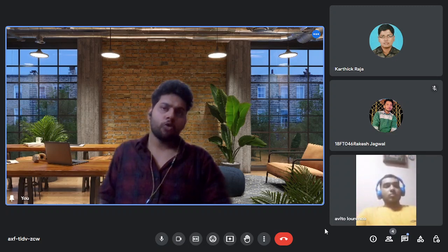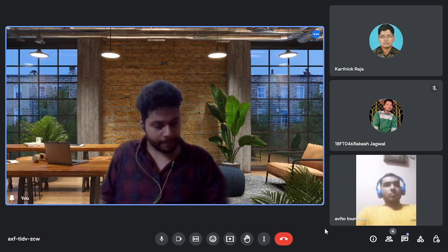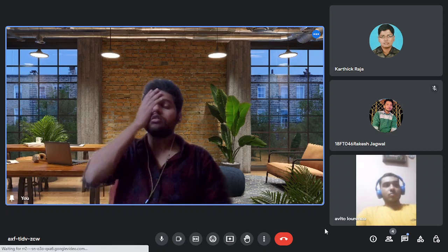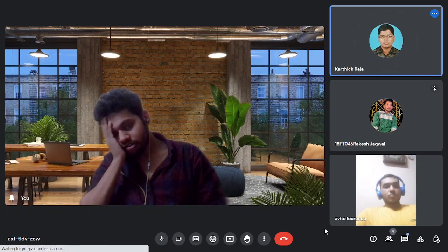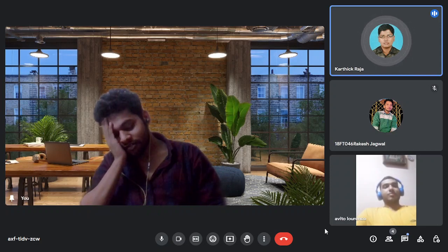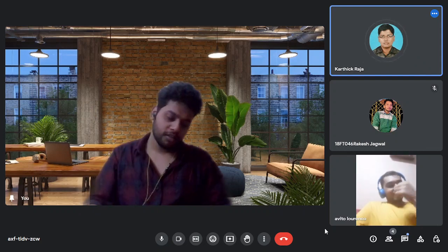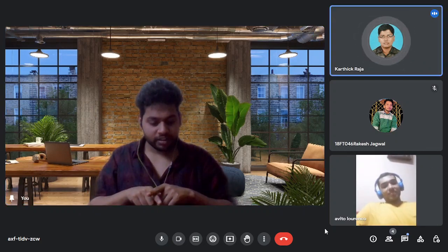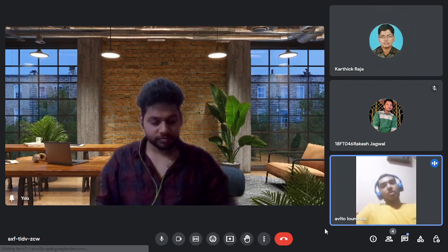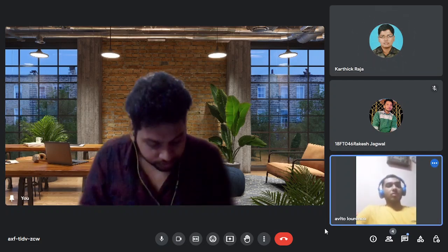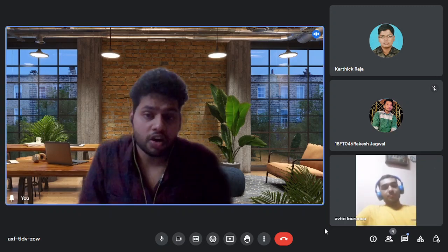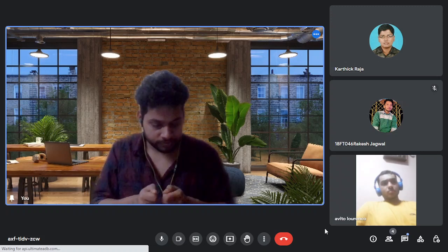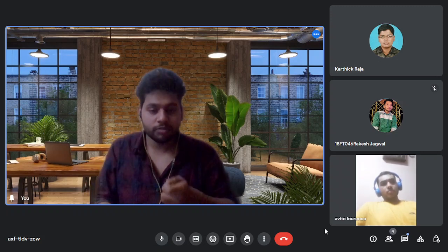It can check the connectivity by checking these three parameters: voltage, current and resistance. If the circuit is open, then the voltage will be zero, or the current will be zero, or the resistance will be maximum. It's just a meter; it just shows a beep sound. It has a digital display also, right? There are two types, analog and digital, and it is not just a beeping sound. It has digital and analog displays, a set of probes or leads, and a selector switch to choose the measurement mode.